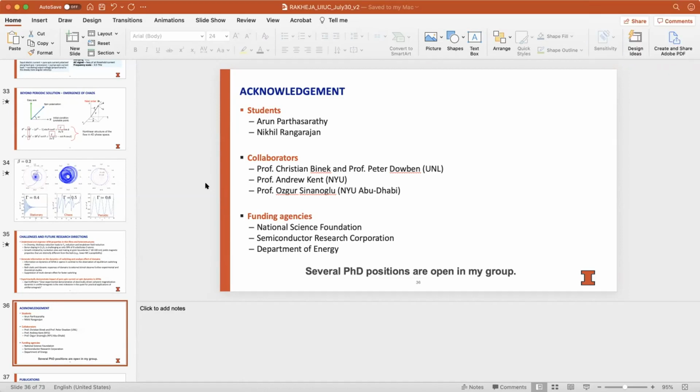Okay, thank you. I think if you're getting into that problem, you're already doing pretty good, because that means your domain wall velocities are approaching the limit, right? For our case, if I may mention one thing, for the samples that I showed you, the domain wall mobility is 2 orders of magnitude lower than theoretically predicted. Yeah, but potentially we would like to switch as fast as possible. So there's a long way to go, I suppose.